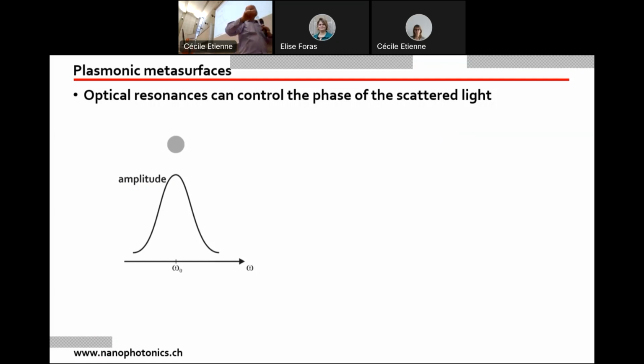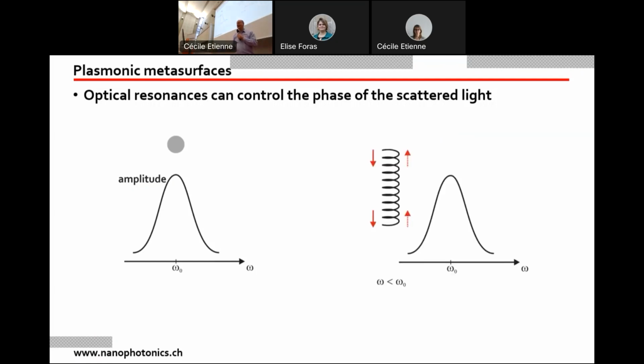So what's happening is just this. If you are at low frequency, before the resonance frequency, we are all in phase. But if you go at high frequency, we are out of phase. When the hand goes down, the mass goes up. So it means there has been a phase difference as we go across the resonance.